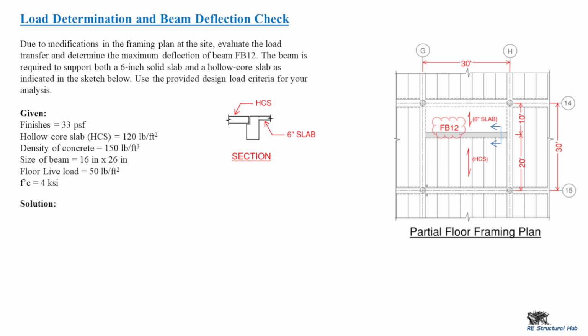In today's video, I'll walk you through the process of determining the loadings on beam FB12 here, as shown in the partial floor framing plan. This drawing is extracted from our previous project, and I would like to share with you how to determine the loads on the beam FB12 and also determine the maximum deflection due to this loading.